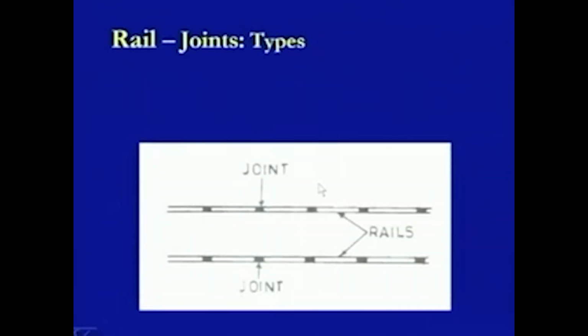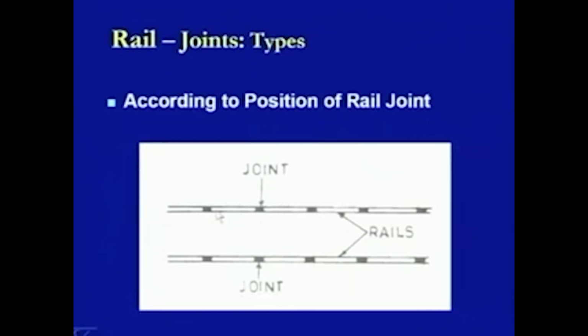What we see is that this is a square joint where these are the rail sections being provided. These are the rail sections on this side as well as on this side, and the joint is provided on this location. It means the joint on the other rail section being laid parallel at the gauge distance is going to be just opposite to this one, and that is how at every regular distance we are going to have a joint on both rails. This is making a sort of square condition, so this is why they are termed as a square joint.